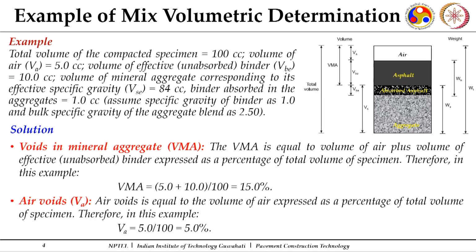In the last lecture, we discussed the different phases of a bituminous mix when it is compacted using aggregates and binder. There we discussed the different volumetric parameters. This is a three-phase diagram. This is your air, this is the binder which is free, and this is that small amount of binder which can be absorbed by your aggregates, and then the remaining is the aggregate volume. So, this is shown in this particular manner.